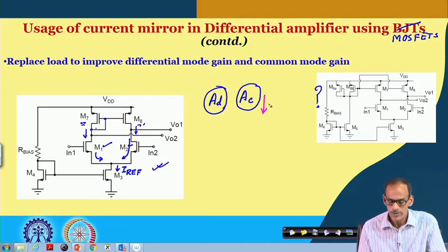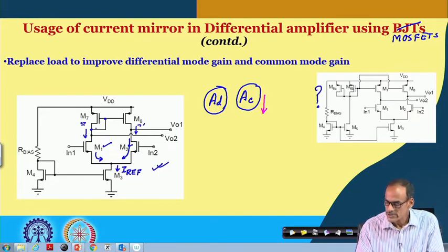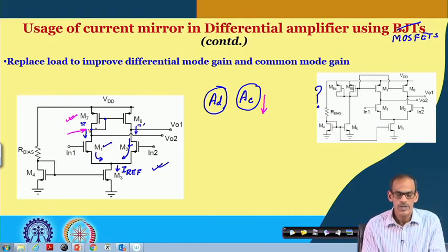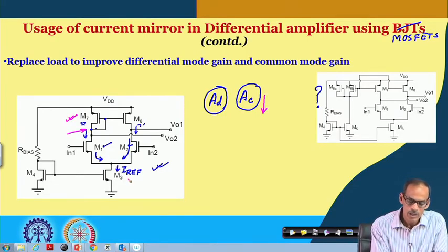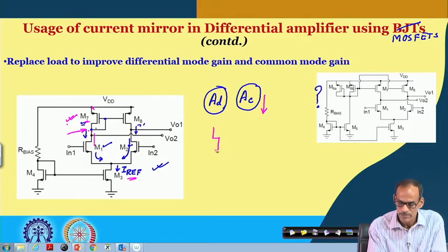From the DC point of view, we also have to keep one important thing here: since transistor 7 is diode connected, the voltage here is pretty well defined. In fact, whatever half of this reference current is flowing here, along with the VGS of this transistor, defines the corresponding voltage here. So, if I draw the left part, we have transistor 7 diode connected.